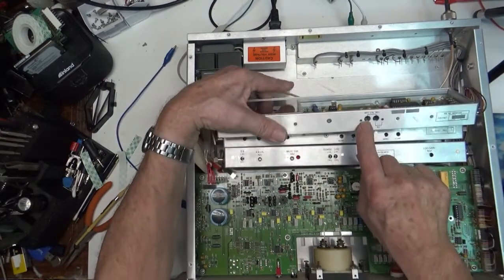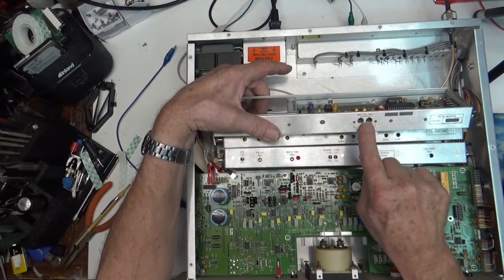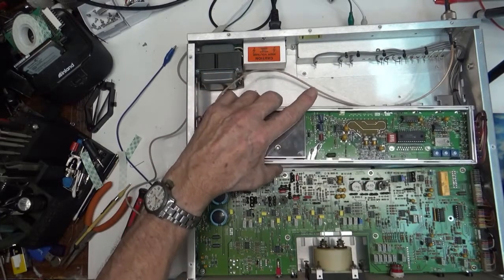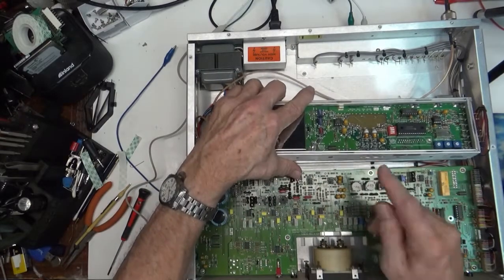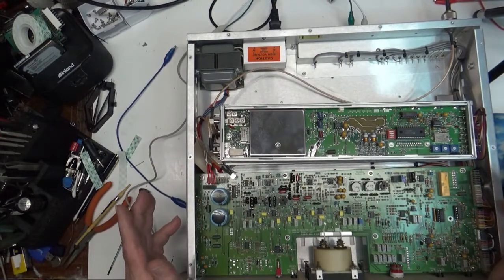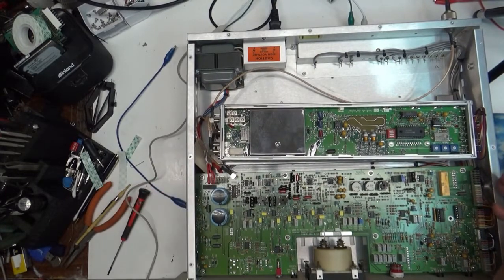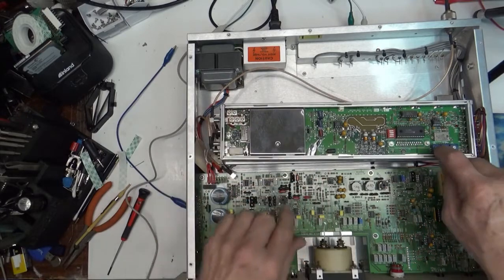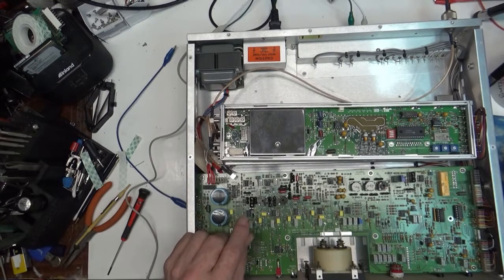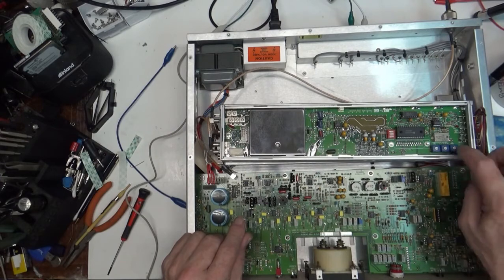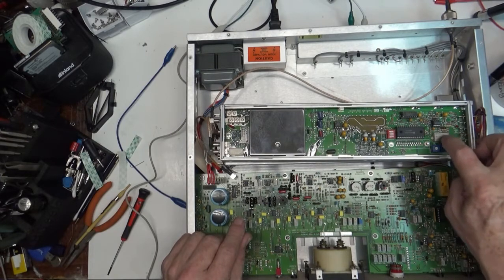Oh, and here's your AFC level adjustments right here. Those are the ones that you use to get your AFC up in the middle of the meter, just like the other one. You just turn those until it comes up to 0. Anyway, that's how you do it. That's how you set these things up. You do the transmitter, get the AFC level set up right. Then you do the receiver with your switches via the calculator, what we just did for calculations. You diddle with this one and the frequency on the transmitter.